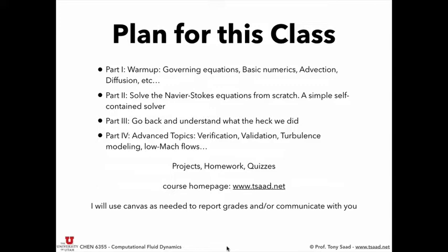But mastery of the governing equations is essential. You need to understand when you say, oh, this is an advection term, this is a diffusion term, this is a source term, this is a gradient term. Diffusion is stronger than advection in this case. You need to understand these concepts. And as we go through, I'll share with you my knowledge about these, but you have to essentially have a solid understanding of the governing equations.